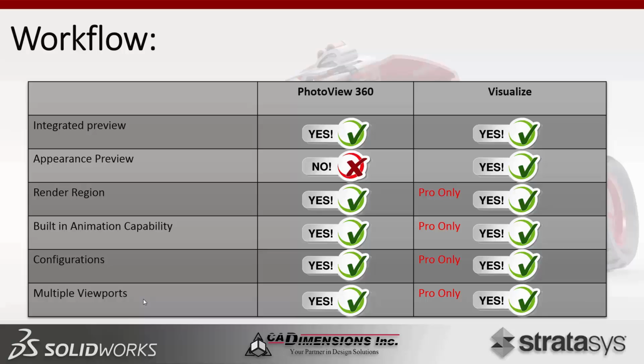Now, render region is an area that I used quite a bit in PhotoView360. Visualize does have it, but I haven't used it in Visualize hardly at all, other than to just play with it. Render region I used in PhotoView360 quite a bit just to improve performance in terms of rendering a small area of the model, so I could get an idea of what's going on in that area. Again, with Visualize rendering in real time, I don't feel like I really need to do that anymore, though it does have the capability. If you have Pro, you can flip that on.